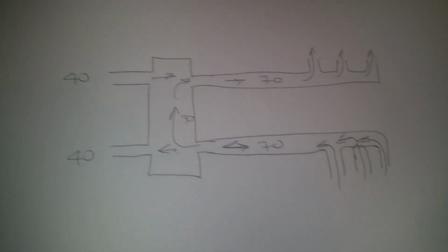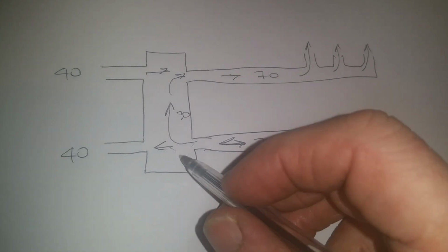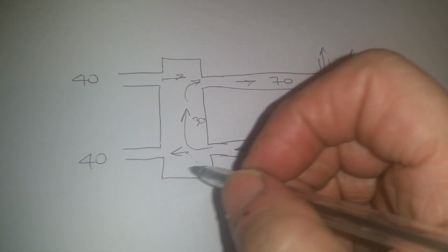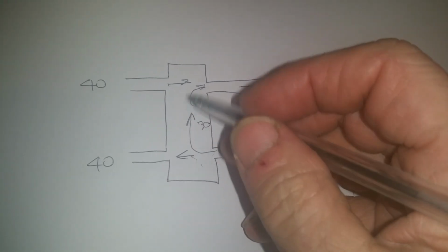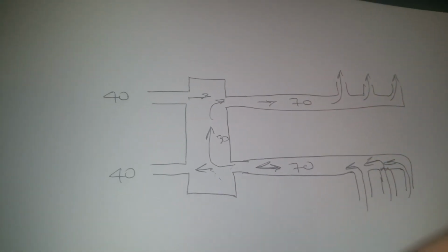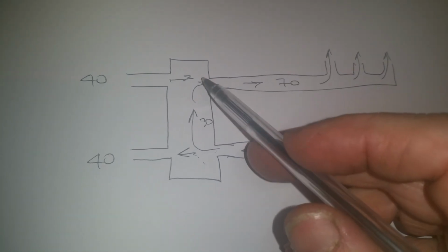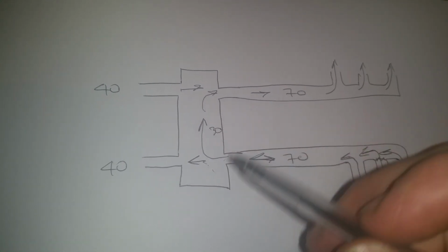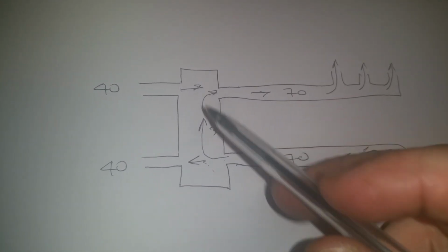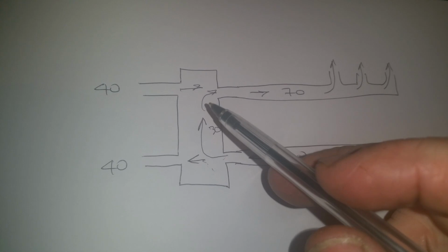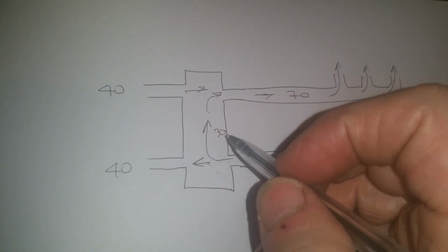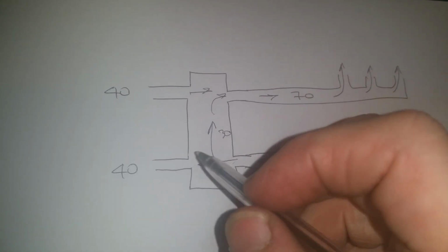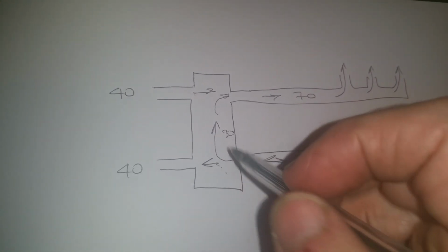So one of the other things I was mentioning was velocity in the pipe here. So the point of a low loss header is that there's almost no pressure loss across this part of the system, low head loss, or low velocity. Sometimes you hear them called low velocity headers, and sometimes low loss headers. More commonly it's the low loss header. And the low loss is low head loss. And so as to get no head loss, which is no pressure variation across this, no delta P, we need a very low flow rate.